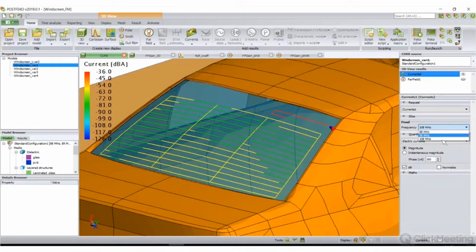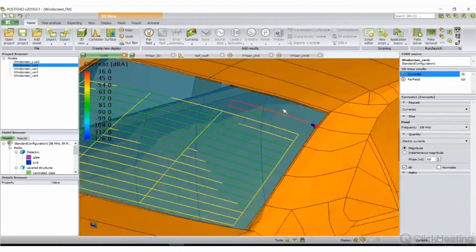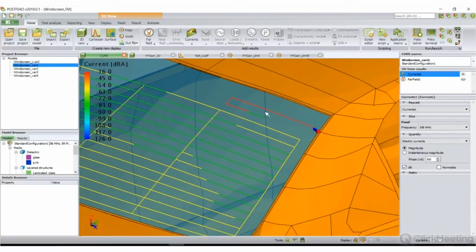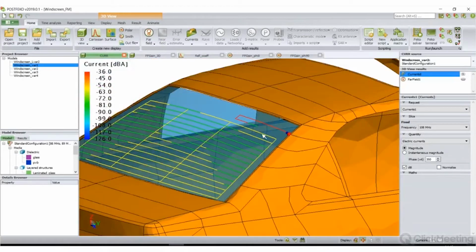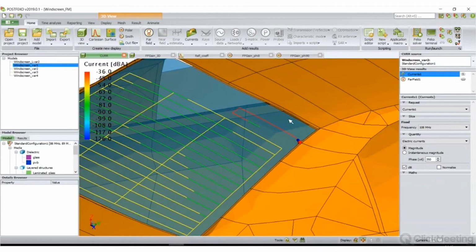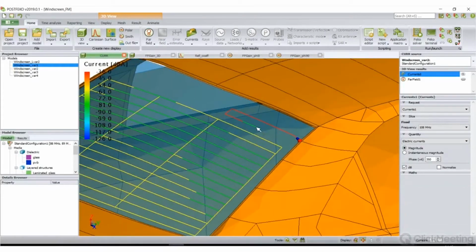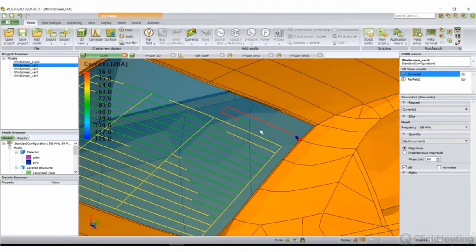Okay. I calculated 3 frequencies beforehand. We were talking about FM radio, so between 88 and 108 megahertz. This is what we're going to be looking at. At 108 megahertz, we have a hot wire, namely our antenna. So we have a really nice, good resonance at this frequency, and we can expect a nice performance of the antenna. Let's look at the other frequencies.